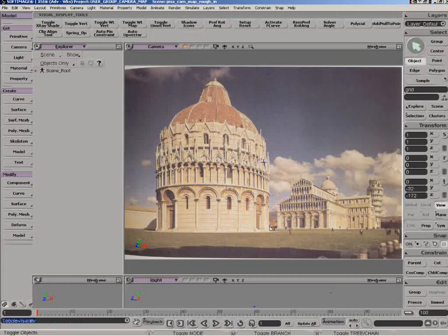One of the visual cues in a potential camera mapping image is the use of right angles in the image. We know that this building is more or less built at right angles, 90-degree angles, in order to create the box shape. What we can do is take a grid or a cube or anything that has right angles on it as well, and match up the amount of distortion. The greater the degree of distortion we see here, in other words, the closer we get to a right angle, a perfect right angle, the lower the degree of lens we'll use in XSI. So as we get closer to a right angle, we get closer to an orthogonal, or to no perspective at all.